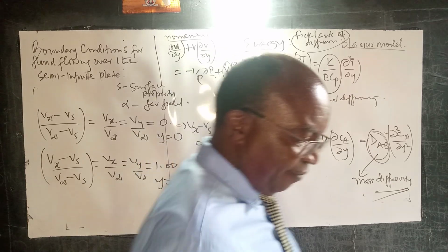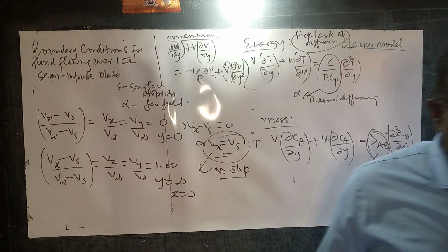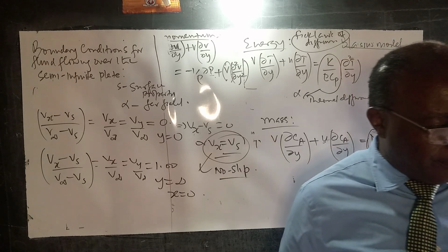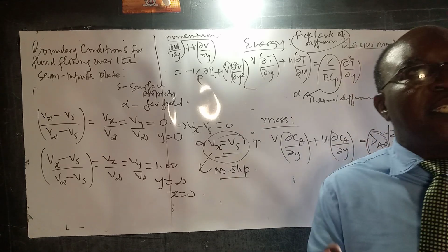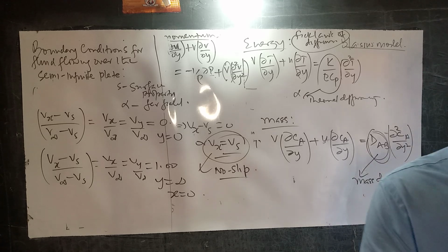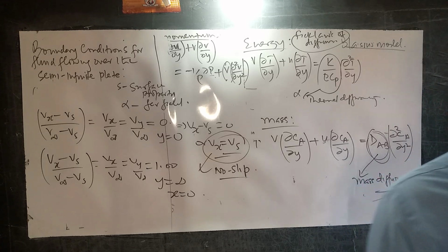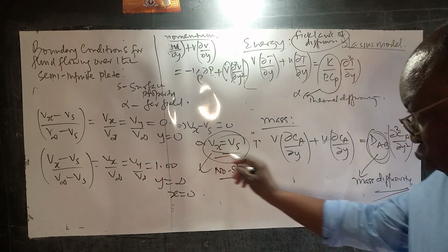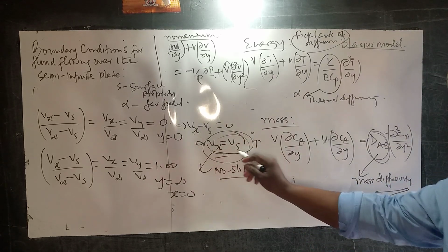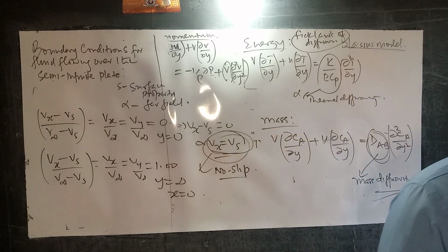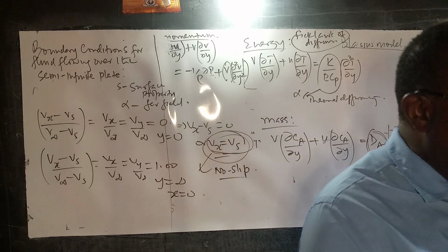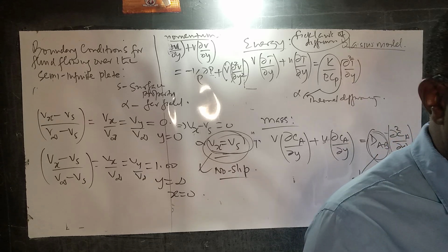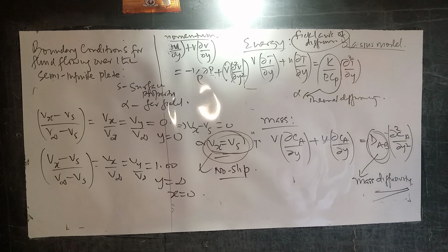which means that when the fluid is flowing over the solid boundary, its velocity must be 0. So think about it in a very simple manner. We have that same semi-infinite plate. What we are saying is that if the two velocities are equal, then whatever the case is, either the plate is stationary, or if it's moving, they're all moving at the same pace.